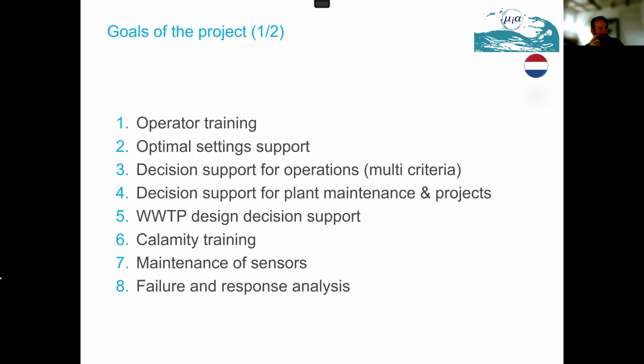And the biggest thing that we saw that operators are interested in is the failure and response analysis. They, of course, get messages during the night when a pump or some other equipment fails, and they can then put that in the digital twin, set the capacity of the pumping station, the air compressors or whatever to a different capacity, and the digital twin can process that, and then they can see if they need to get out of bed or not.